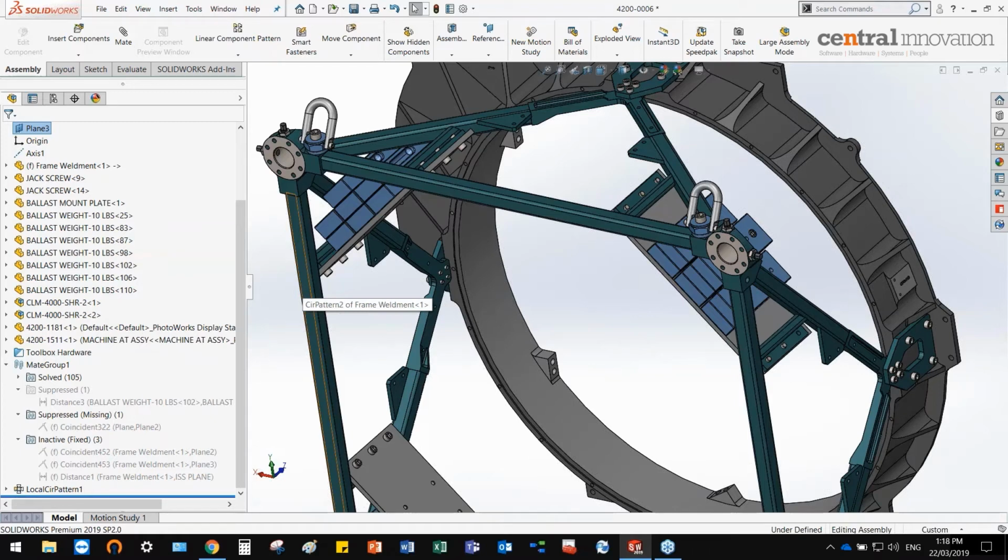However, in practice, I'm sure we've all found that you're modeling and modeling and modeling, and it's very easy to forget to hit that lock rotation checkbox within your concentric mate as you're putting parts in place. So you can end up with parts that are not properly constrained as you may want them to be, just in the course of modeling.